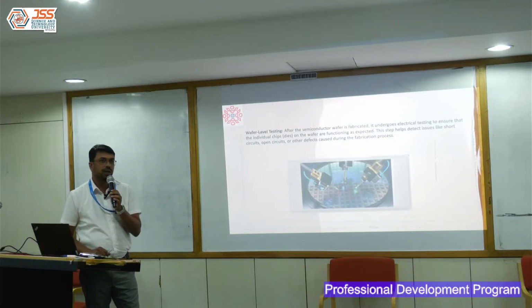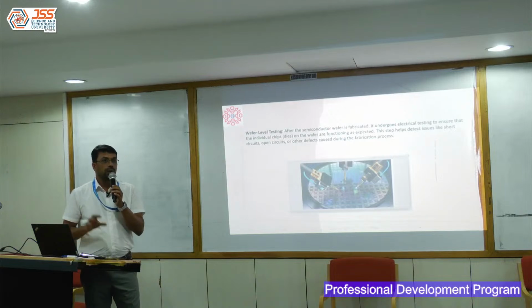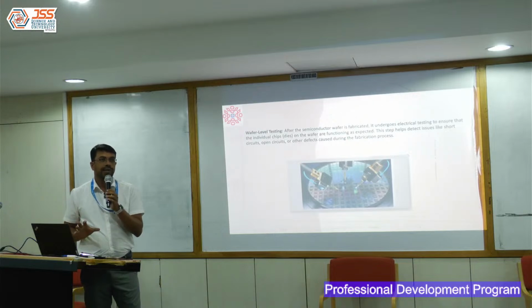They bring out that component and again run some parametric testing. So they will get to know what is the degradation. Based on that, they can say, okay, this chip will work well, or they can give an expiry saying this is for 10 years. Post 10 years, we cannot guarantee its performance, it can degrade.